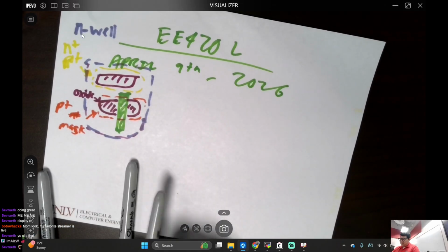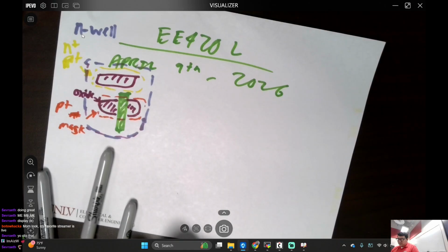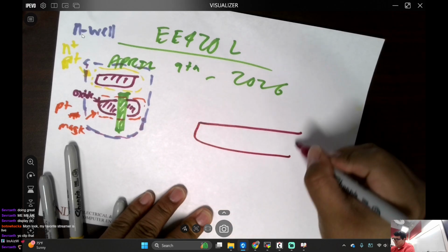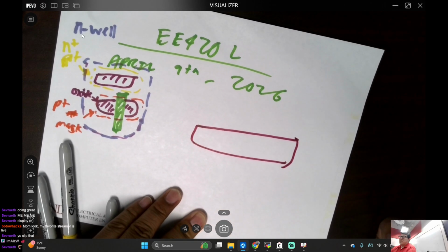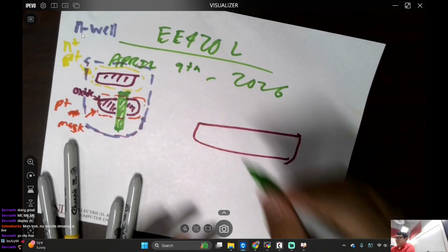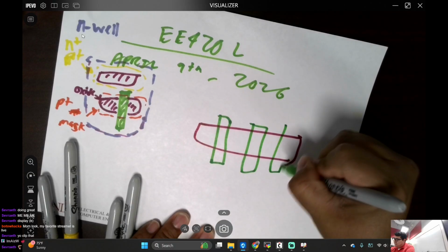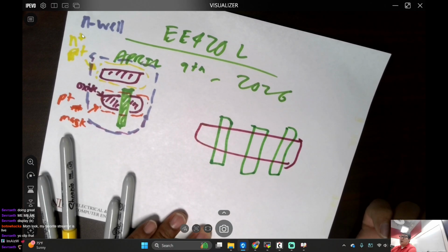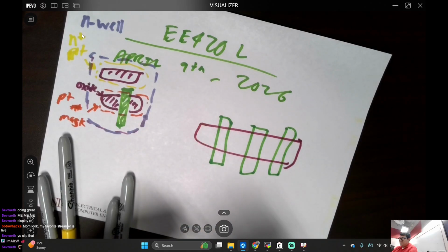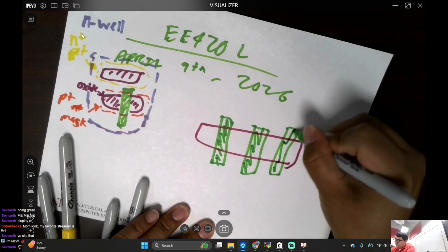So how do I do it for a multiplier? Let's just do 3, okay? So what's the first thing I'm going to do? This is what you do as an engineer. Draw this really long piece of oxide, correct? It doesn't do anything right now until we do the following. When there's poly on top of an oxide like this, now we have transistors. It's pretty cool, right? Color that, color that, color this. Cool.